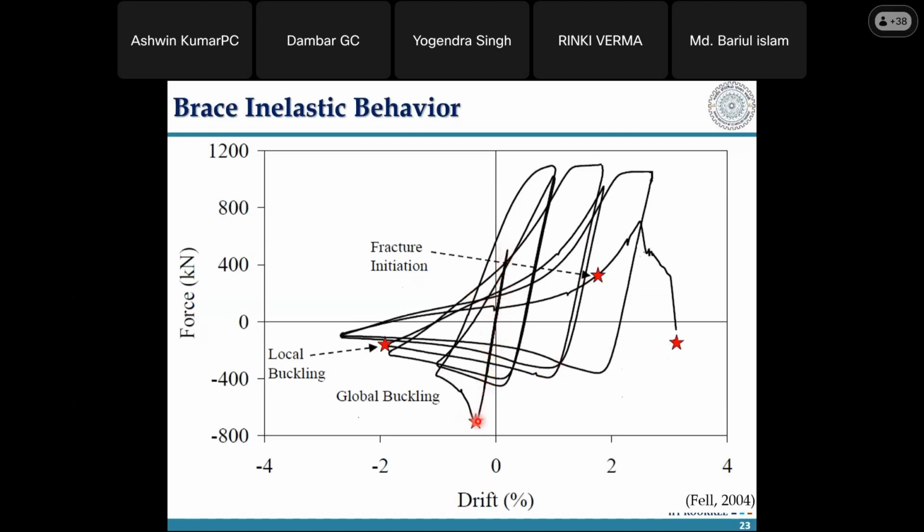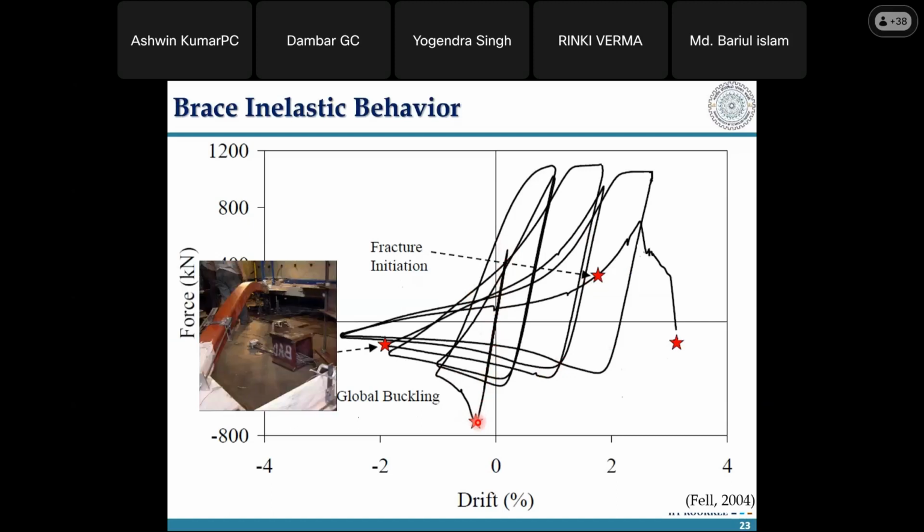And when the deformation increases, the first event to occur is the global buckling in the member. You have to understand, event-wise, that it occurs at around 0.3% interstory drift; it buckles right there, right? You have to understand that 5% lateral drift is the maximum drift criterion that we expect before the connection fails, where we don't want entire collapse of the structure to happen, where we want maximum braces in the system to have undergone yielding and buckling, and minimum energy dissipation has happened. But the event of buckling visibly occurs around this 0.3%.